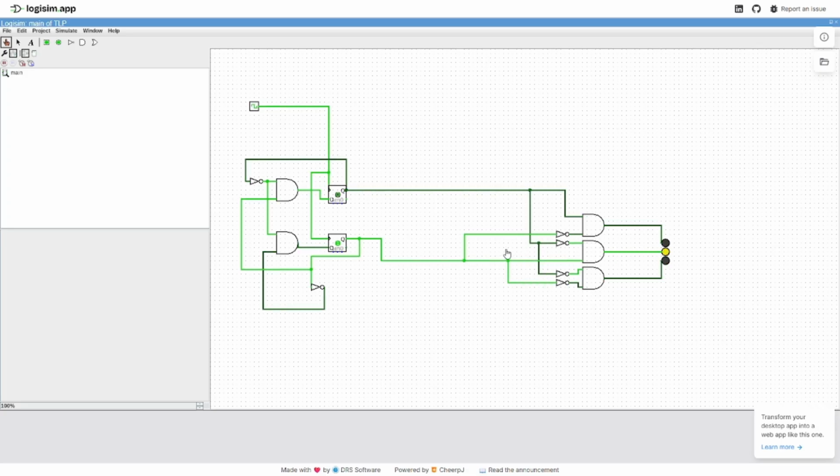So in the yellow state, the third output will run and send one signal to the AND, and the second one is 0, which with a NOT will be 1, and the output will be 1 to the yellow, while the green has 0 from the first D flip-flop, and with a NOT it will be 1, while the second flip-flop will be 1, and with a NOT will be 0. Into the AND gate it will be 0, and the green light will be off. It's the same on the red light.